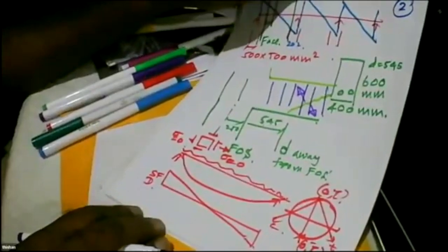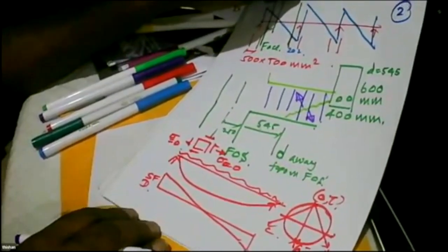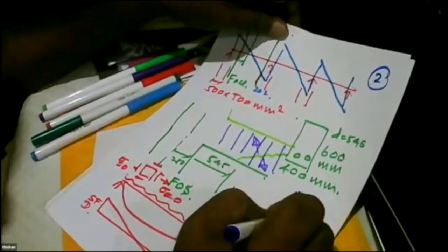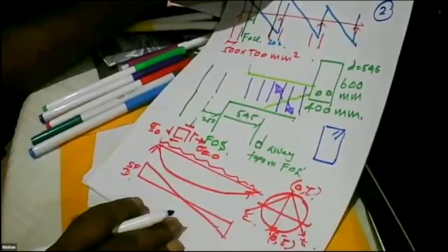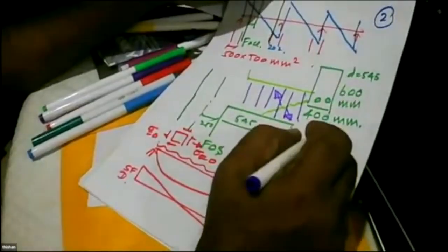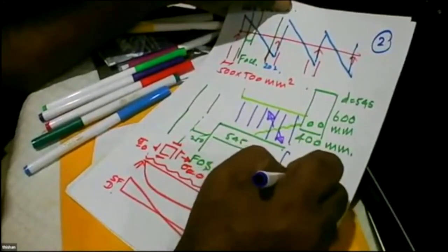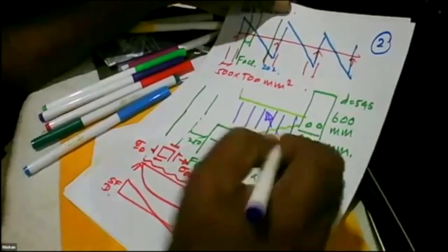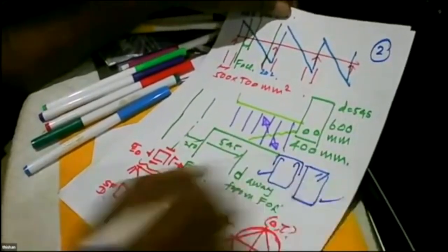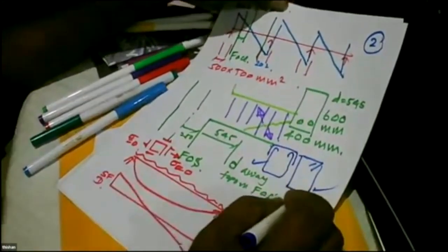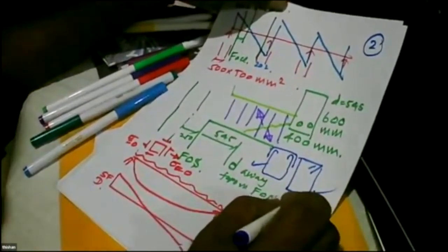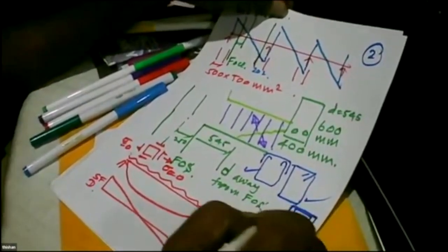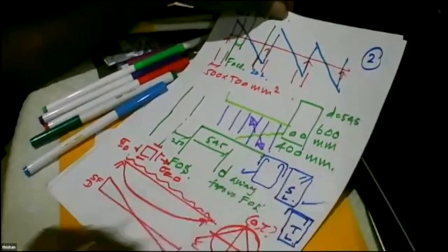Vertical reinforcement should be properly anchored. So what we say is vertical reinforcement should be in the form of links like this, closed links, or this shape. But we can have a closure. This is also possible. This is also possible. But this is called a torsional link. These are called shear links.